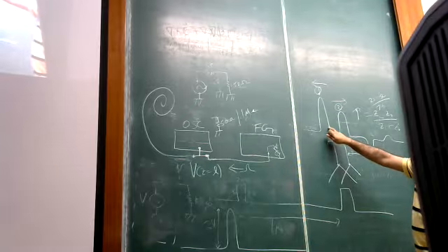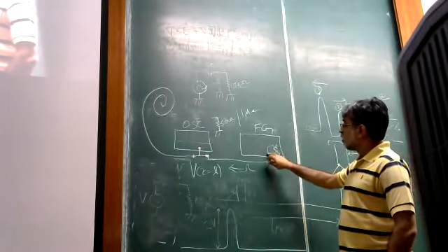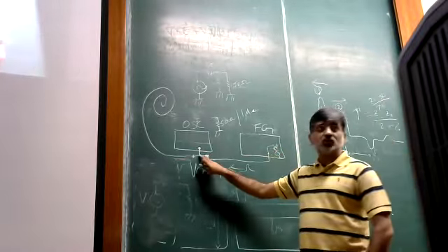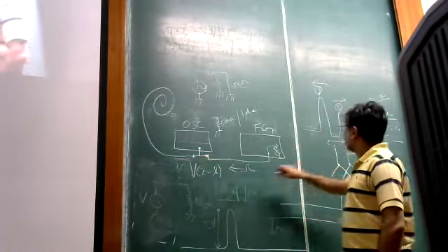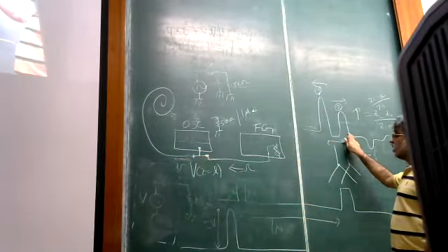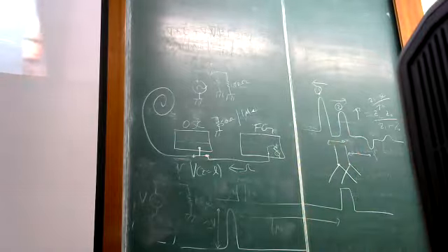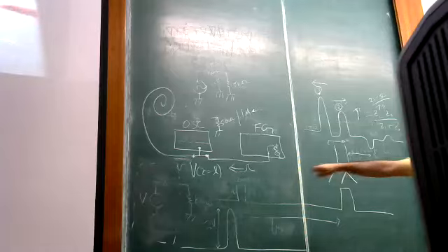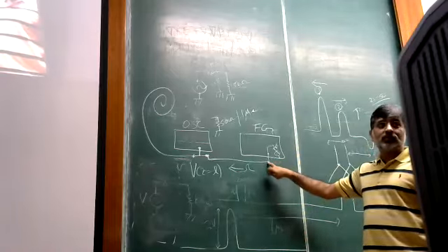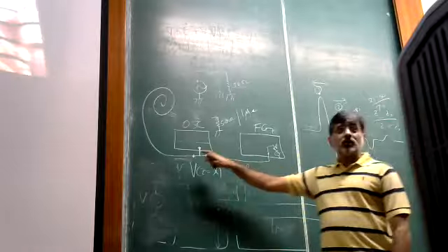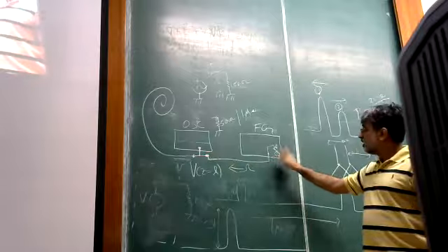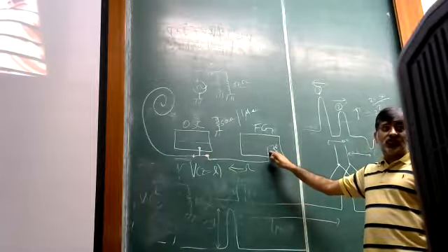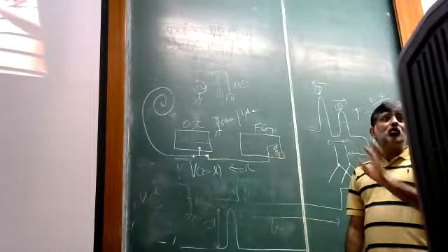This pulse, the first one, is when the pulse from the function generator arrives at this junction for the first time. Well, you have to be more precise. Which amplitude? If I check the amplitude here, then it's not the same. Because when the pulse is launched, the function generator is seeing a 50 ohm transmission line.